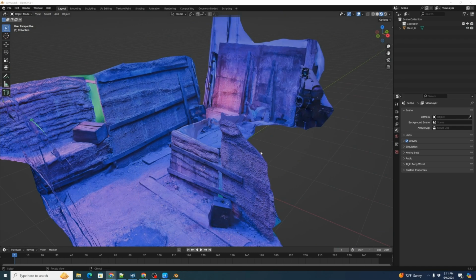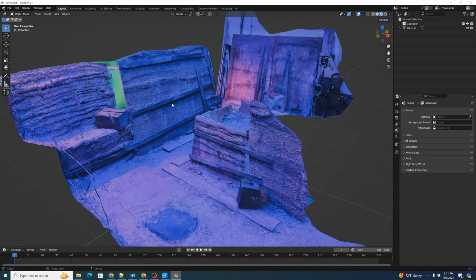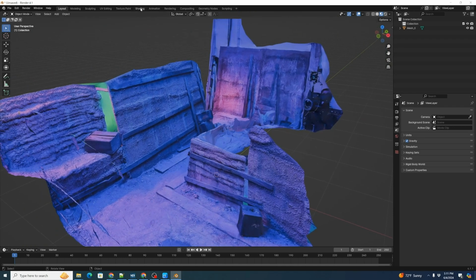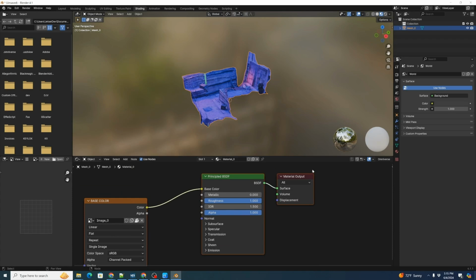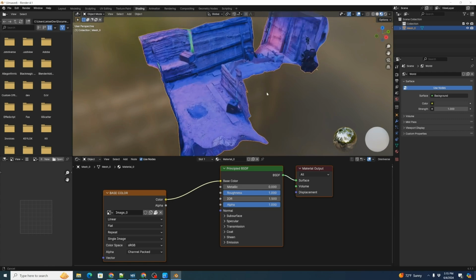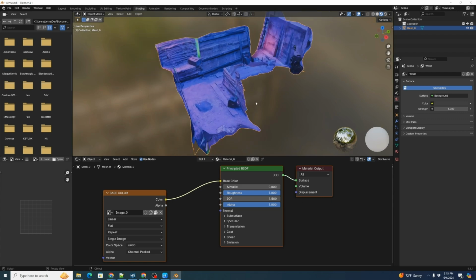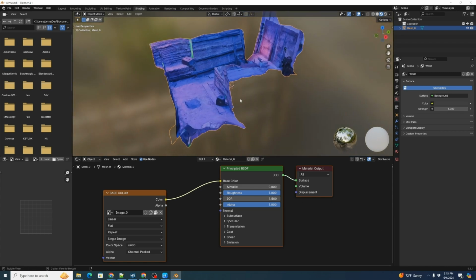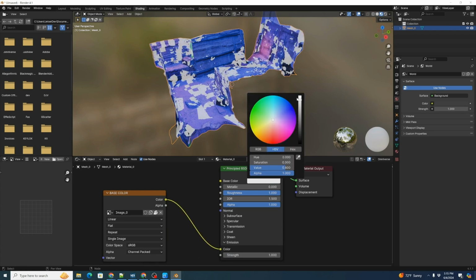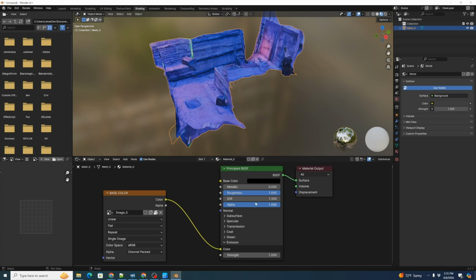First of all, let's do some material definition fixes, because the way this is imported, it won't work quite right in Jetset. So let's fix that. We're going to look at this in the shader tab, and we're going to do some shader changes here to make it more of an emissive color rather than a standard base material that would expect to be lit, because inside the phone, we don't really have much of a lighting system. So we're going to open up the emissive, change our color to here, change our strength to 1, and change our base color to 0.